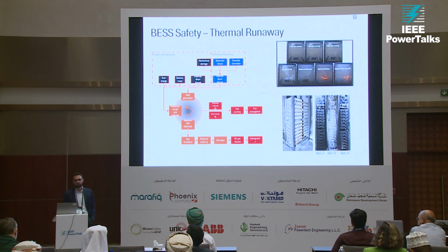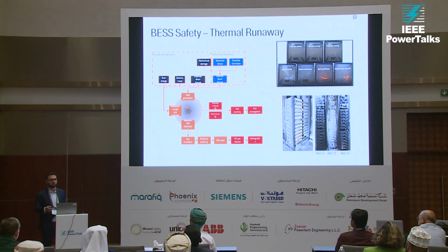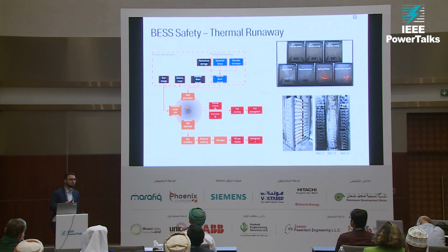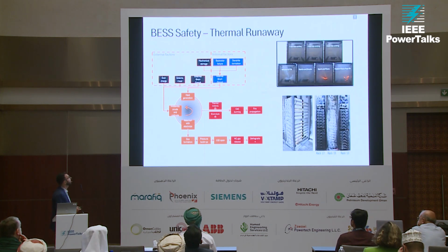That's what we'd like to keep them most of the time. That's why we introduce the cooling systems. But in some instances, let's call it subsystem failures or hotspots in some of your systems, bad thermal management design, you get some of these cells to go into higher temperatures, and that results in a thermal runaway.